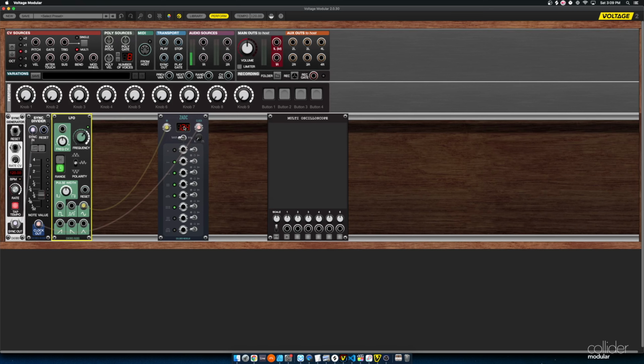This number is then taken and it is converted into its binary representation. And in binary, 255 is represented by 8 ones or zeros. And so you can see where this is going. There are 8 output channels of Zadc, and each time there's a 0, the gate signal on the output jack will be low, and each time that there's a 1 in binary, it will be high.